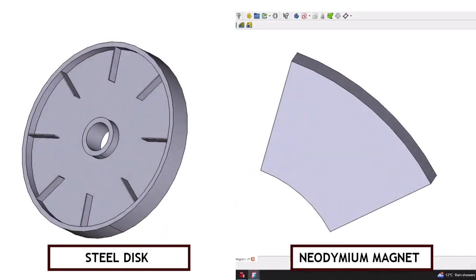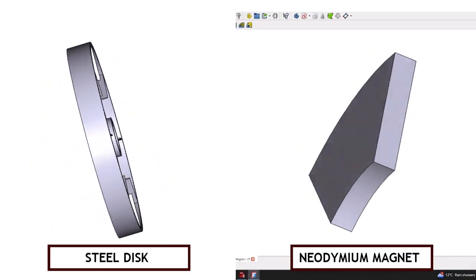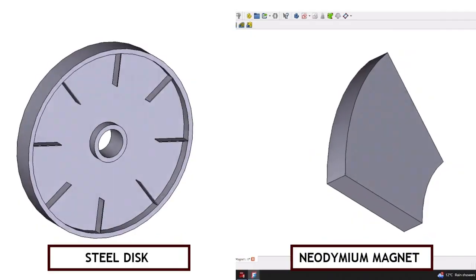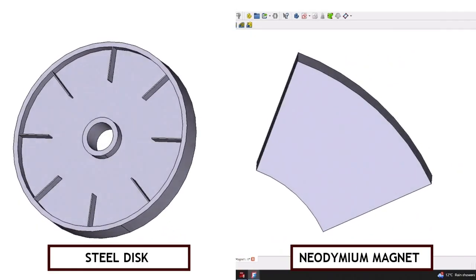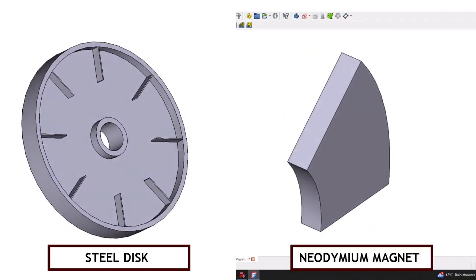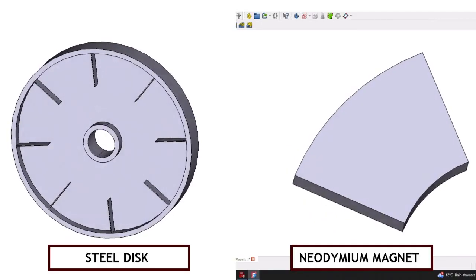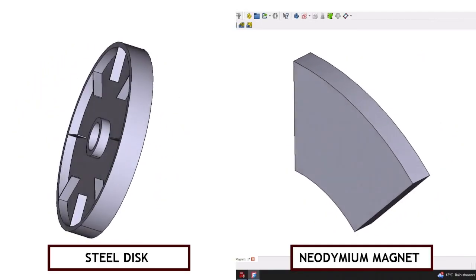So I designed such a machine, and I was in talks with a local engineering company who were going to do the machining. The machine was going to use 64 largish neodymium magnets, 8 on either side of metal discs, fitted in slots, fixed together, 4 discs mounted on the same shaft, and I calculated that that would produce an output voltage of 12 volts if spun at 4,000 RPM and possibly 10 kilowatts of power.